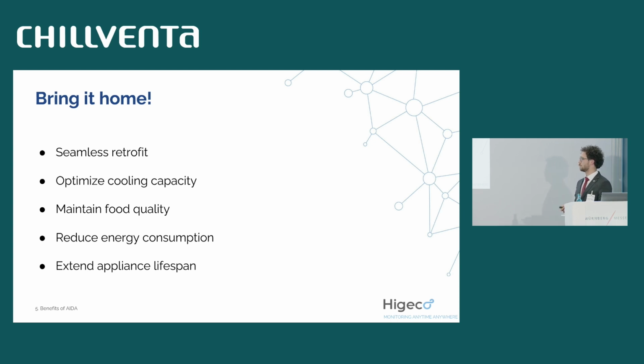And of course, we are reducing the energy consumption since on average we did several fewer defrosts than in the base case. Finally, this should result in an extended appliance lifespan, since we are stressing the whole system less. In particular with hot gas defrosting, we have fewer cycle inversions.